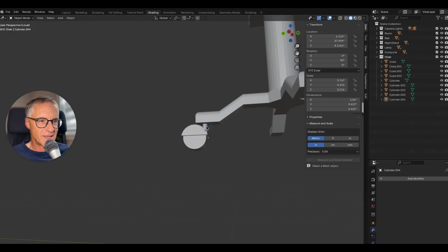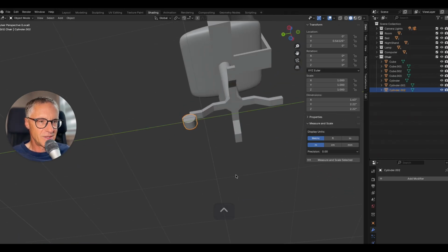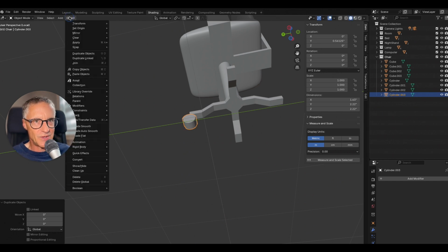So we'll select the pin. I'm going to call it the housing and the wheel. Do a Command J to join those all together. And then we just got to do a Shift D, rotate Z. So again, here we're going to have to set the origin to geometry.